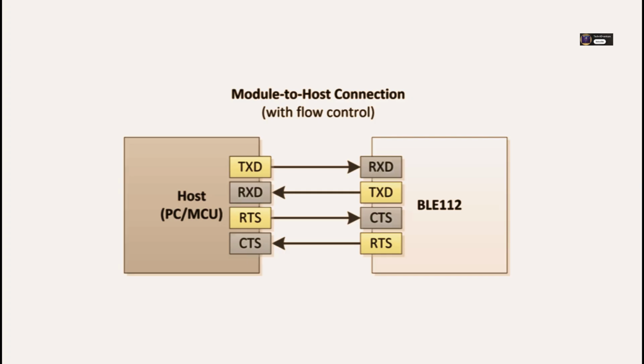RTS and CTS, how do they work? It's like a handshake. The device that wants to send data asserts its RTS line, basically saying, hey, I want to send. The receiving device will only assert its CTS line when it's actually ready to receive data, e.g., its buffer has space. The sender must check that the receiver's CTS line is asserted before it starts transmitting data. If CTS drops, the sender pauses. It's a very direct, hardware-level way to manage the flow and prevent buffer overflows. Very reliable.